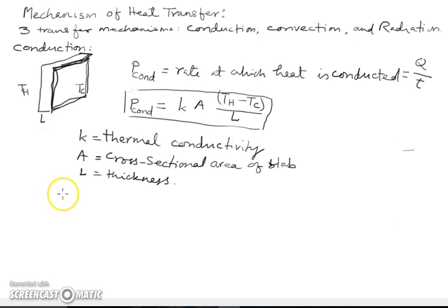Couple of units. K is thermal conductivity, so unit is going to be, let's say P. What's the unit of P? P is joule, is energy over time, so watt. So watt, and then this is meters, so this is per meter, and then per Kelvin. And of course the unit of P, or heat transfer rate, is joule per second.